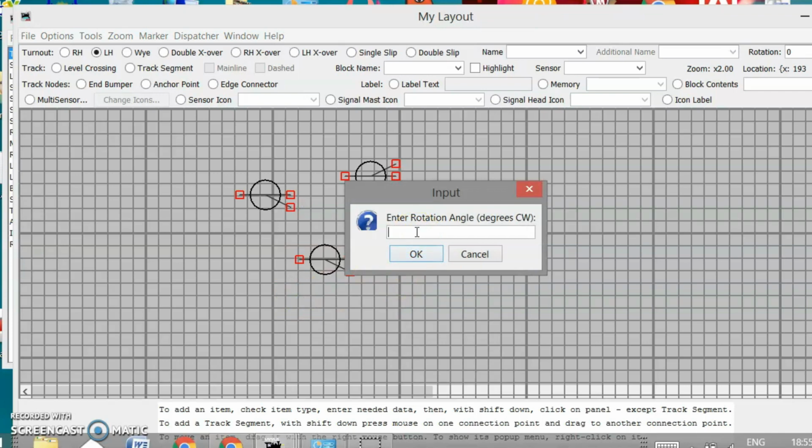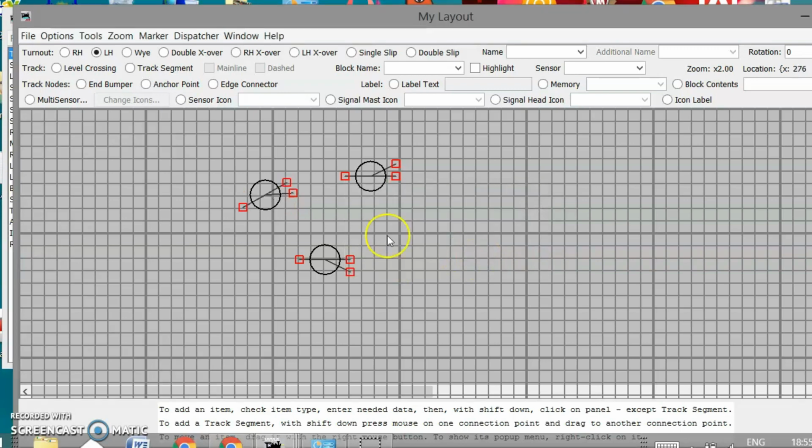We haven't assigned the addresses yet, but I will be using that as 101, rotated to, let's say, 30 degrees. So as you can see, I have rotated, I mentioned minus 30. For some reason, I don't know why, the positive rotation actually needs to be marked as negative in JMRI, and negative needs to go as positive. So it all depends on frame of reference. I just don't know which frame of reference they use.